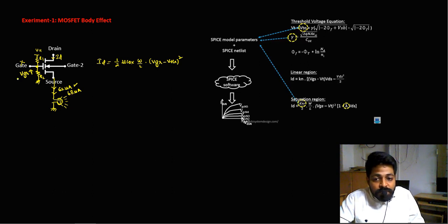So now my solution is, as we know the gate terminal, this is my body terminal, which is called the second gate. Across the body terminal I can give an external voltage, where it was grounded as of now. Now I remove the ground and give 0.1 volt over here. Now I will give 0.2 over here. Like that, if I increase the voltage across the body terminal, I can observe that the current flow can be increased.